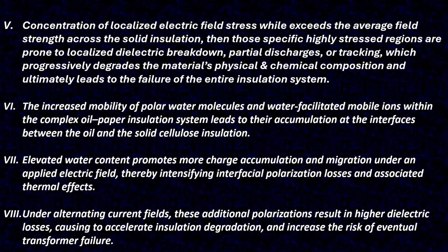Elevated water content promotes more charge accumulation and migration under an applied electric field, thereby intensifying interfacial polarization losses and associated thermal effects. Under alternating current fields, these additional polarizations result in higher dielectric losses, accelerating insulation degradation and increasing the risk of eventual transformer failure.